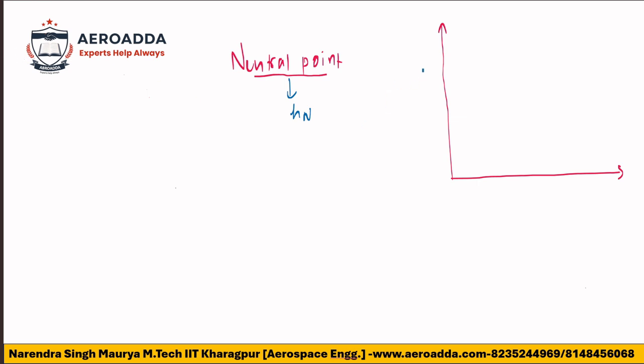Take it. CMCG you had seen, this is the CMCG, and here you had seen alpha. Now if I say the slope is this, correct? Multiple times I have shown this is the slope. This slope is nothing but ∂CMCG/∂alpha, and that is negative.